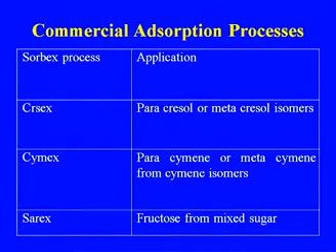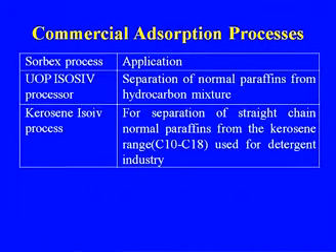Cresex for paracresol, Cymex for separation of paracymene, Sarex for fructose. These are some other applications of the adsorption process. This is one of the adsorbents developed by UOP for the separation of normal paraffins from hydrocarbon mixtures. The Kerosene Isosiv process is for the separation of straight chain normal paraffin from the kerosene range, used for the detergent industry.